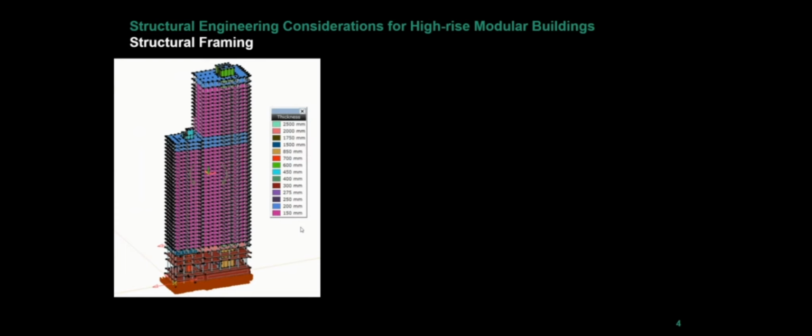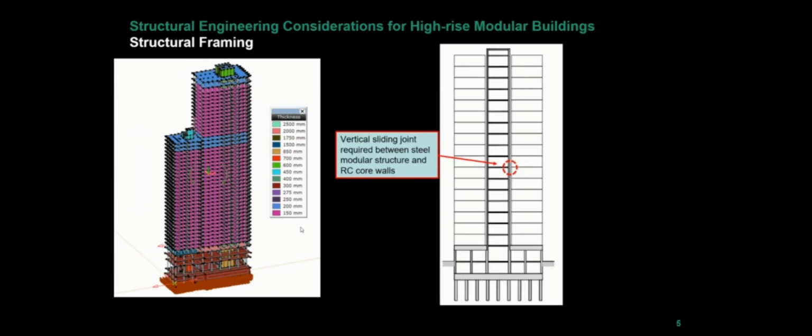You can see this screenshot on the left hand side is 101 College Road, and you can see there the thicker, in blue, modular floor slabs we would have had at the step in the buildings for the permanent high level forces. But as Michael discussed, due to the temporary forces, the rest of the modular slabs worked at the thinner 150 mil thick slabs once we tied the cores in the temporary case. On to the next slide.